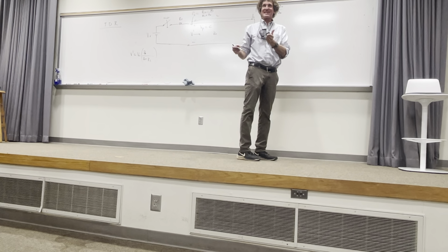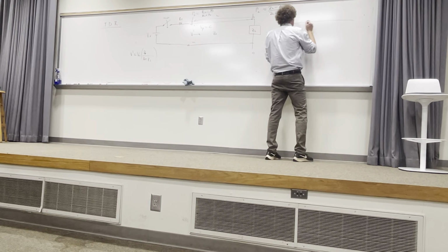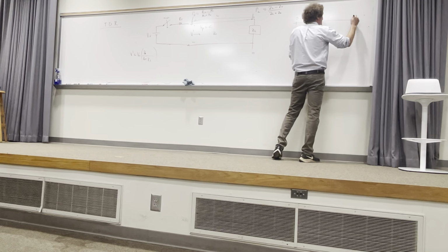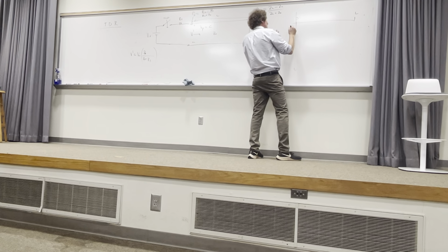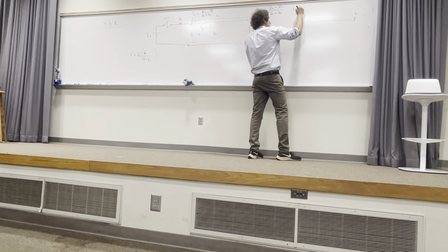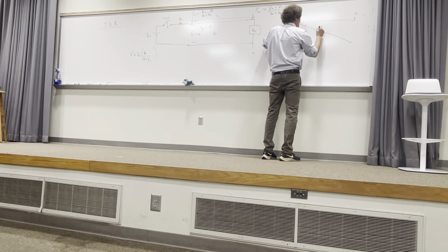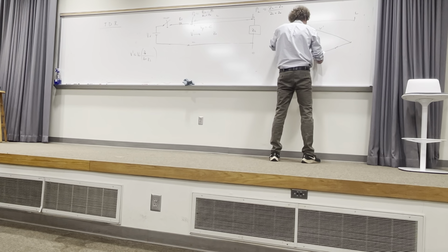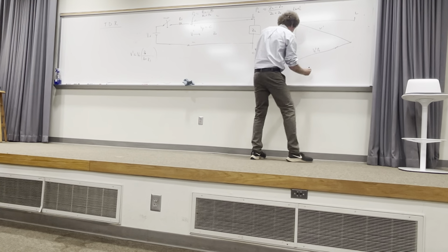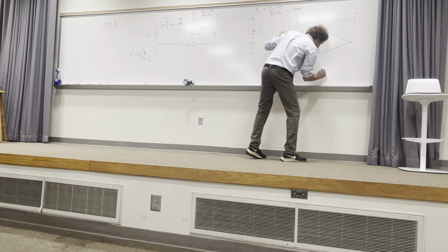Well, the way you do this, without getting sued, is it's called a timing diagram. But here, you put the length of the line, this is going to be 0, and then they put the length here, where it is, and they just do this. You're going to just have to bear with me here. This is going to be time in this direction, going down. And what you're going to do is start with a pulse. It hits, this will be V prime. It hits, it comes this way, there's going to be something that says V prime times reflection coefficient of the load. One this way that says V prime times reflection coefficient of load, reflection coefficient of this source.